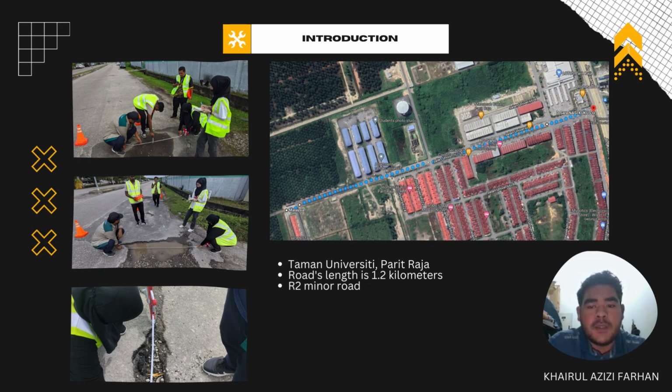In the pavement condition index, we determine the distress type, distress severity, and distress quantity. There are 5 factors used in the assessment of pavement condition, which are density, deduct value, total deduct value, corrected deduct value, and pavement quality qualified.